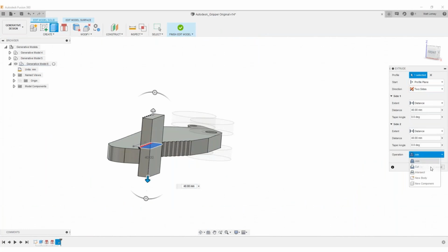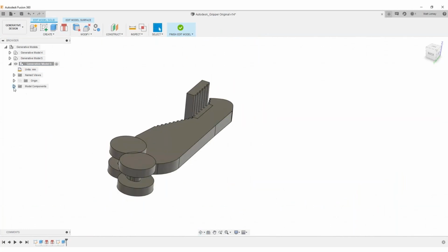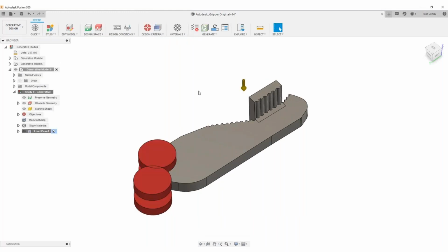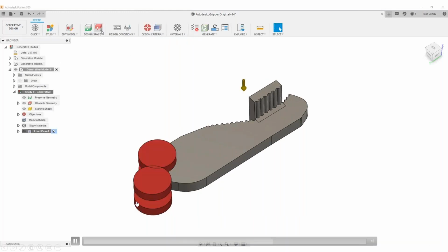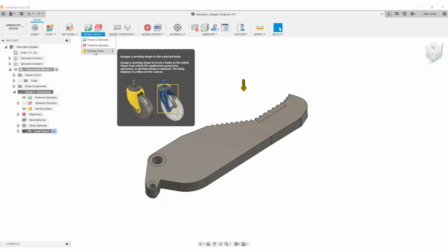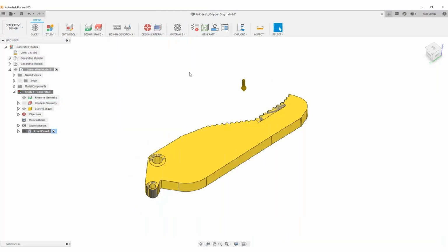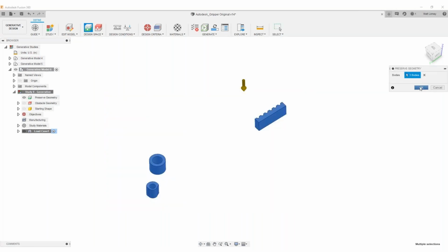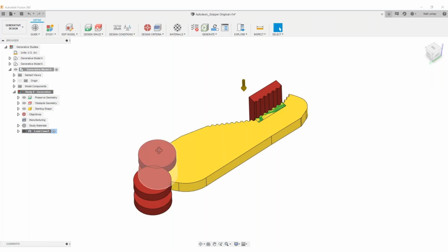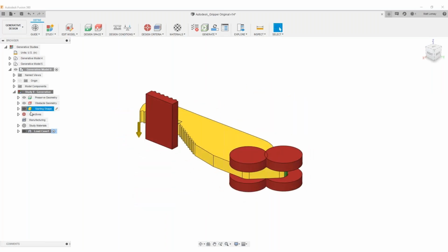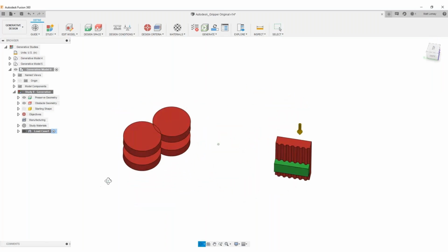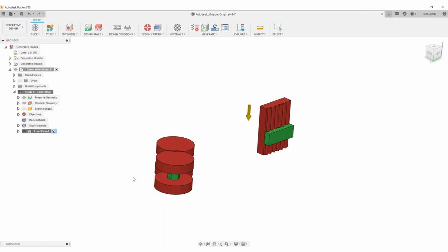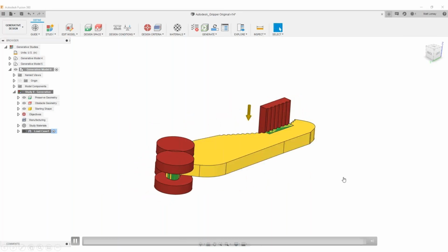I've done those in Fusion 360 in the generative design environment because, for instance, some of them get recognized automatically as obstacles. Then I define the additional obstacles. Then I define the yellow part as a starting shape and the green part as preserve geometry.